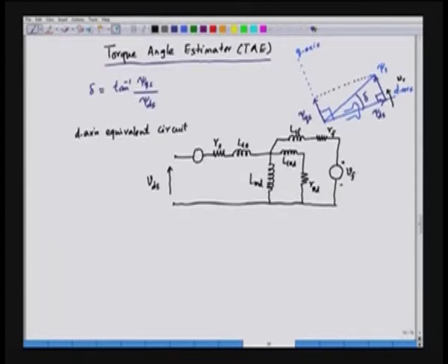All right. So, these are the variables that we have here, the parameters, and we have the current in this case. This is the D axis stator current IDS. This is the damper current in the D axis entering this junction, that is IKD, and this one is the field winding current, that is IFD. So, we have to find out what is the magnetization current, and the magnetization current in this case in the D axis is IMD.